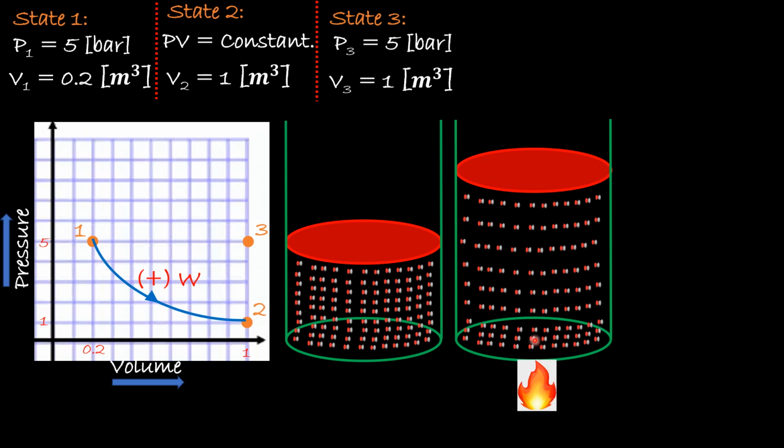That pressure increased because we introduced heat. And remember, what we did in this process is that we held the volume of the gas constant. The volume of the gas didn't change. We were able to change the pressure by increasing the temperature. So when you increase the temperature, you increase the pressure. If you decrease the temperature, you decrease the pressure. All right, so right here, the process goes from state 2 to state 3. Question: what is the work for process 2 to 3?